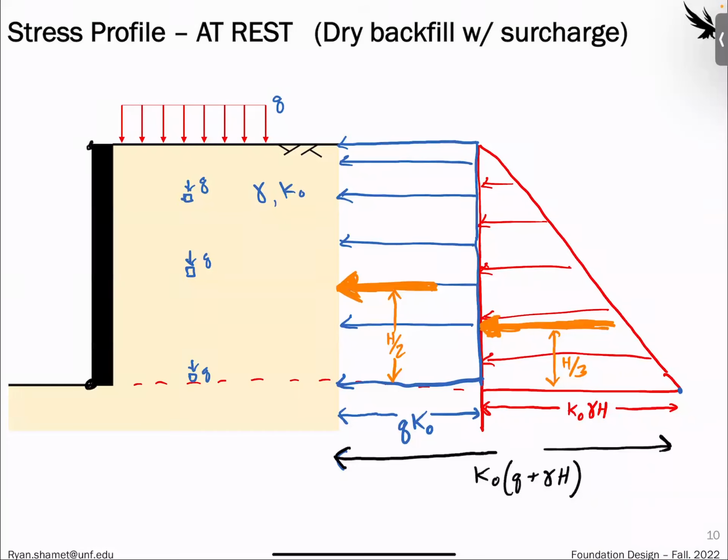So let's just say right here, we'll use the same statics terminology. So A, we'll just take the sum of moments around A, and we know this is equal to 0, and we set a positive direction or whatever, just like we would do in statics. Now you have these two known, and we know that there should be a resultant force. I'm just going to show the resultant somewhere between them. And then what you would do is say that this is some unknown distance z between the two.